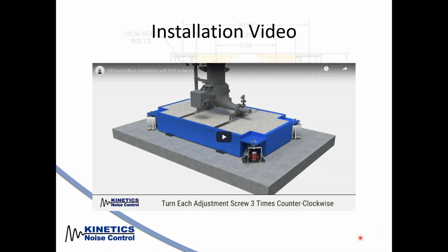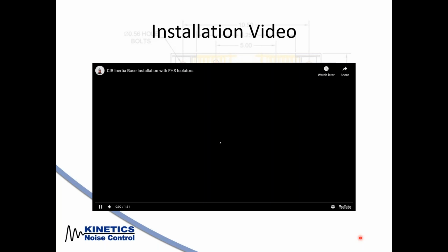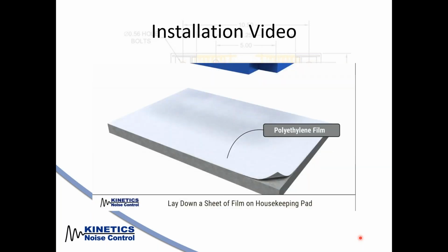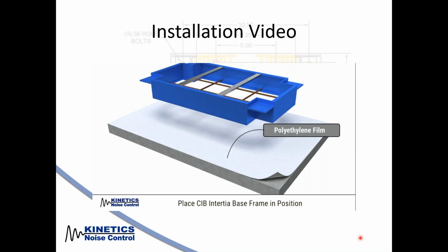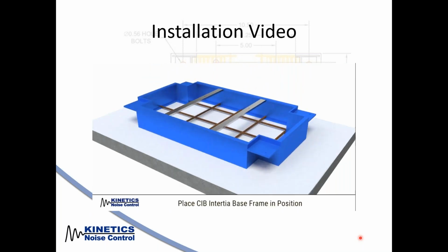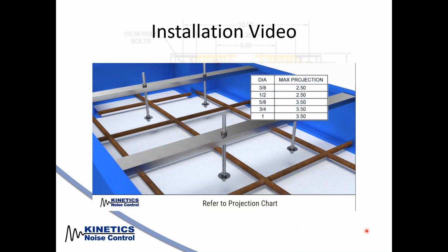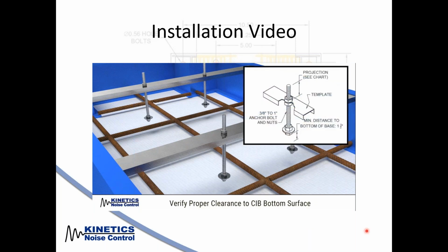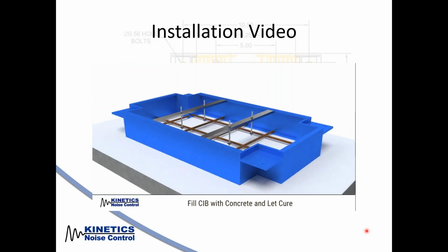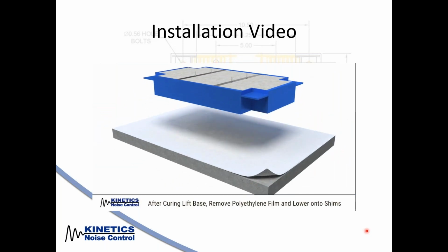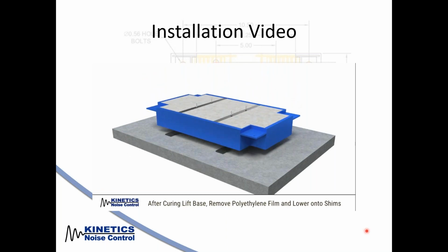We also have the same thing available for our concrete inertia pieces. So anyone on site who is unfamiliar with the product can scan their cell phone over the QR code, and it's going to launch the YouTube video right on their phone or tablet. This one's showing some predetermined threads there for the pump to mount to, and then you're going to fill the base with concrete, and then the same kind of concept with adjusting the isolators correctly. All of these videos are available on the Kinetics website, as well as the QR codes that come on the product.